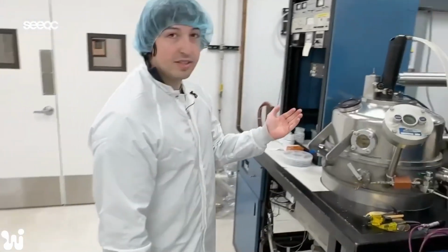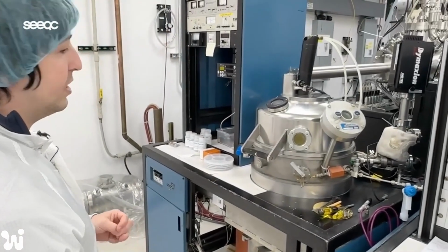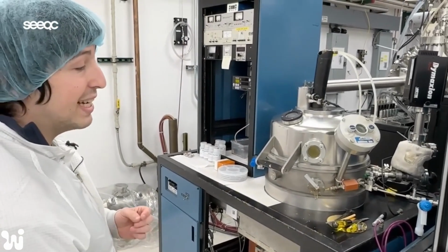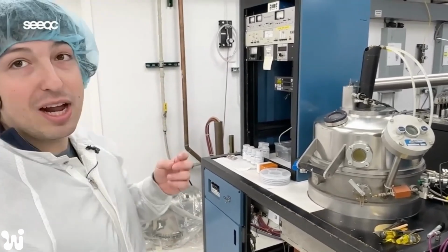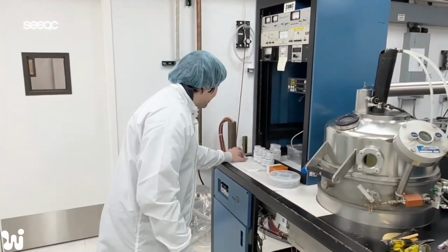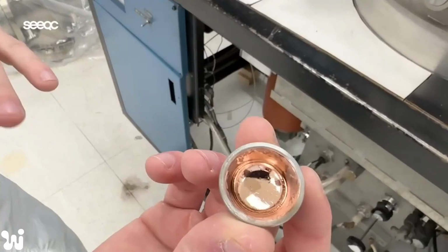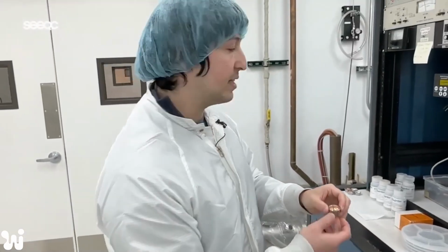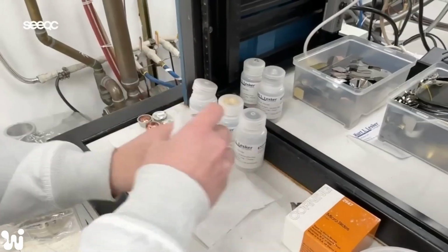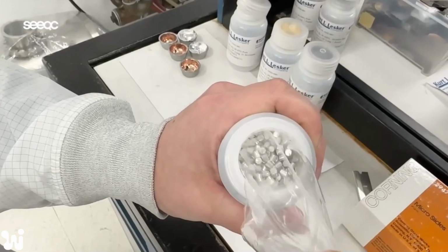This is an old evaporator that we can use to deposit layers of titanium and mostly indium. It works by using electrons to melt metals in a crucible like this to the point where they evaporate and float up onto the wafer that's above them. So you get a very thin layer that's more evenly dispersed. You have these little metal pellets that go into the crucible, and they're melted when they're hit with a beam of high energy electrons.